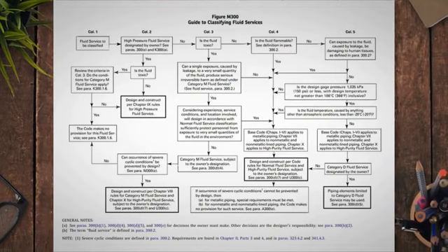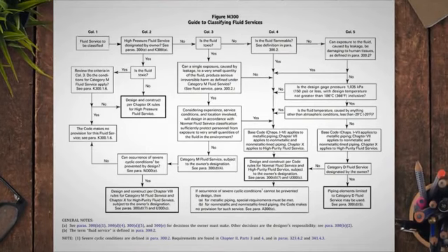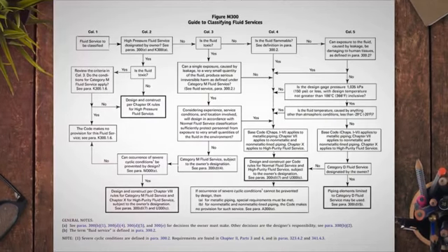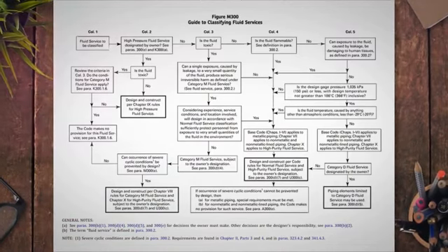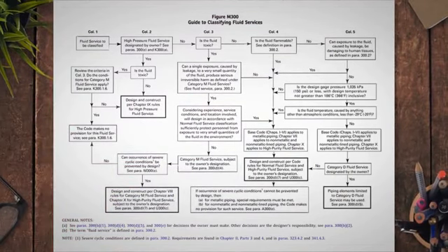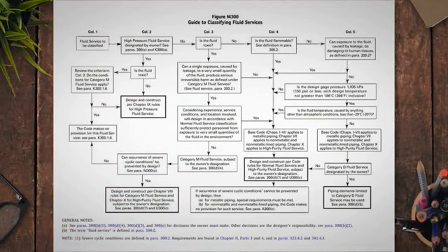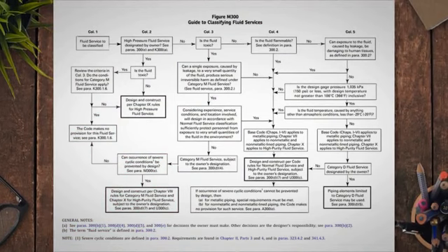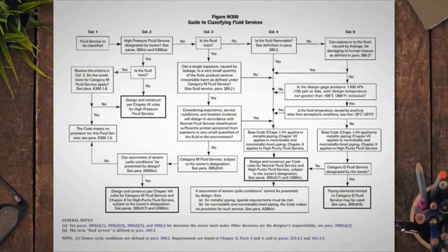Additionally, the design gauge pressure of Category D fluids is below 1035 kPa, 150 pounds per square inch. The design temperature is limited below 186 degrees Celsius, and the fluid temperature is not less than -29 degrees Celsius. Examples include water piping, and cost-efficient construction rules apply to less hazardous services.